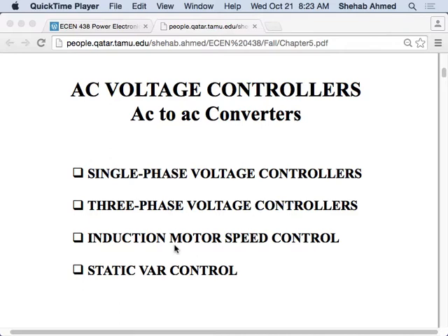But if this piece of wire is wrapped around the core, for example, and this core has time-varying flux going through it, then there will be a voltage developed across that piece of wire. That voltage, if you've properly chosen the number of turns, can equal the amount of voltage that you're putting in, or you can have a small difference. If you have a small difference in the voltage, then you will push current through the transformer. Induction motors are the same thing.